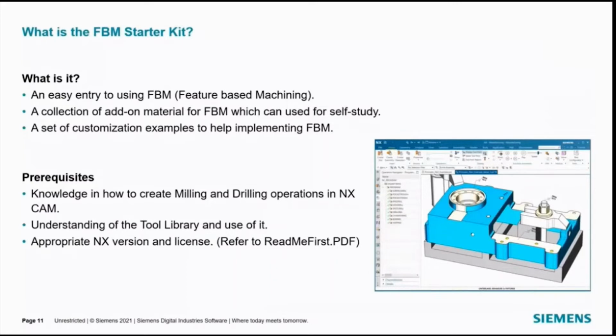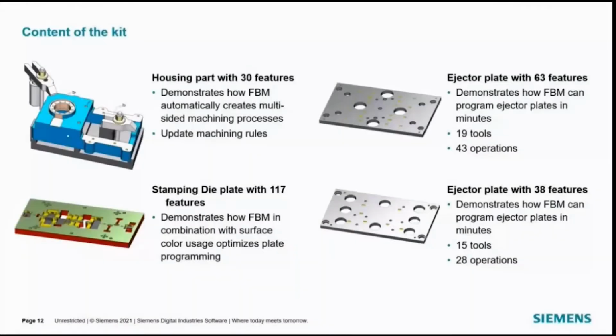However, the kit does come with predefined machining processes, which allows easy modification directly in NXCAM. The kit also comes with a predefined standard tool library, including feeds and speeds. The only prerequisite is NXCAM knowledge, especially how to create milling and drilling operations, as well as an understanding of the tool library and use of it.